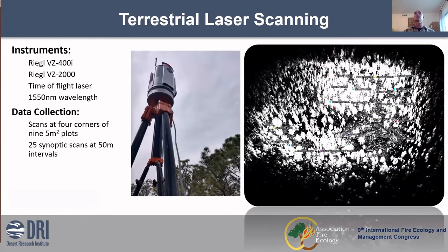And so in this study, it launched this 3D fuels element that we've been working on for the last 3 years, using terrestrial laser scanning as the basis for how we're able to scan large units as well as localized units. And we used two lasers, a Riegl VZ-400i and a VZ-2000. These are time-of-flight lasers.